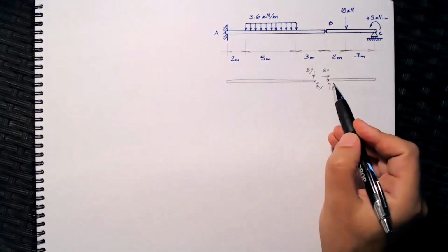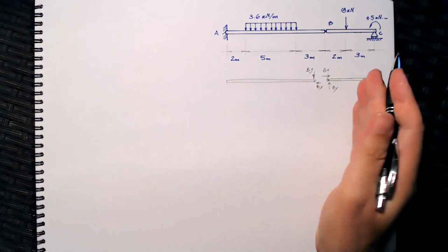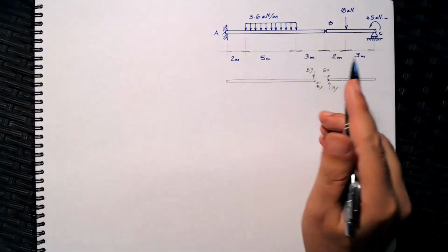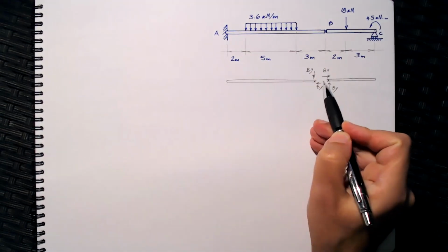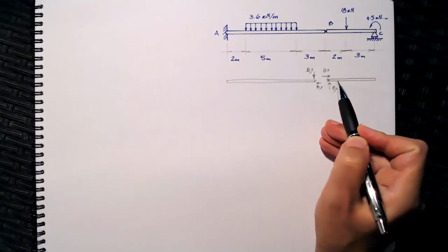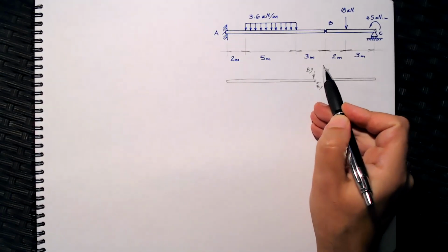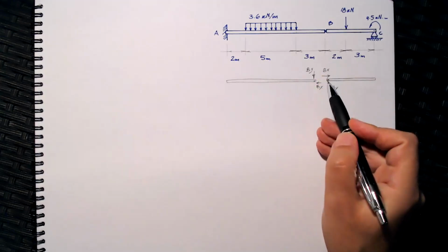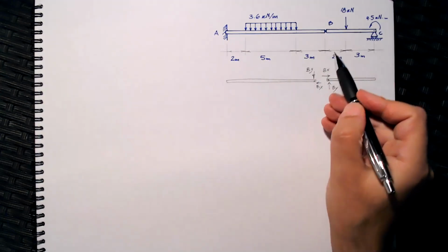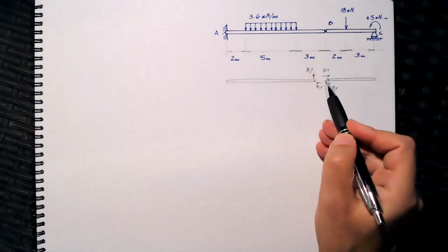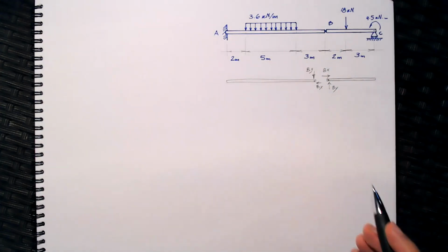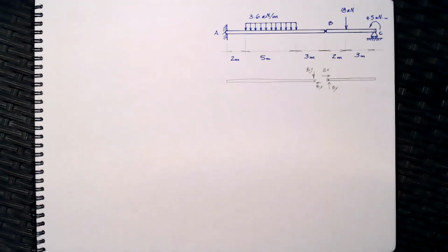So the interesting thing is when you put the right-hand side and the left-hand side back together, you will see these two equal and opposite forces. They cancel each other. These two equal forces cancel each other, and this leaves the pin joint in equilibrium the same way we found it. So these forces, when you put them back, will cancel each other.